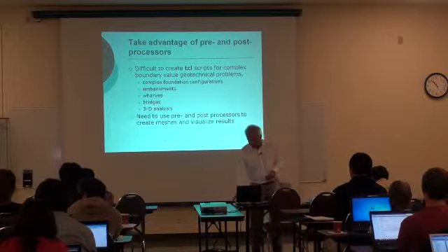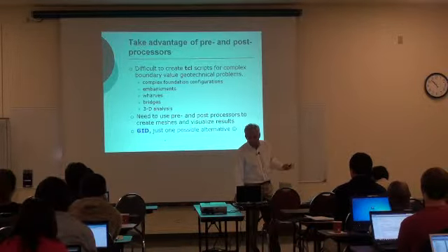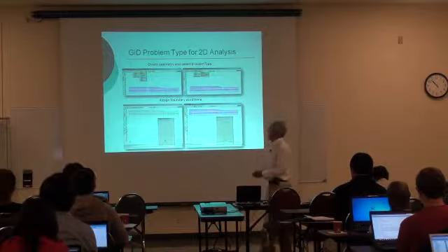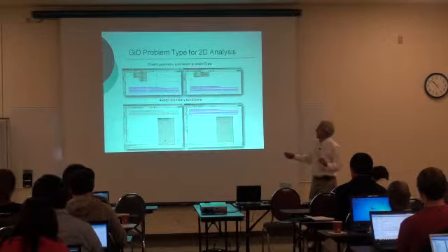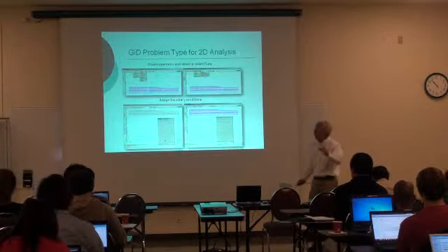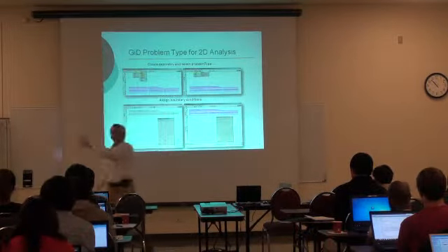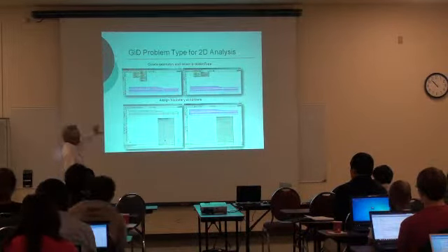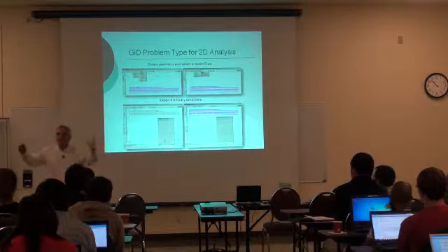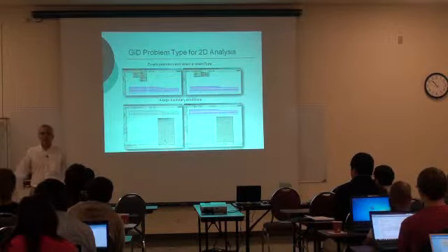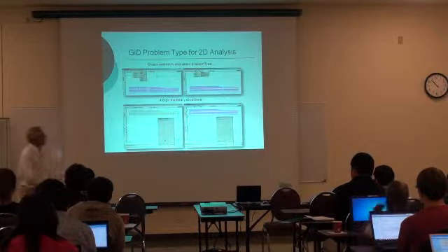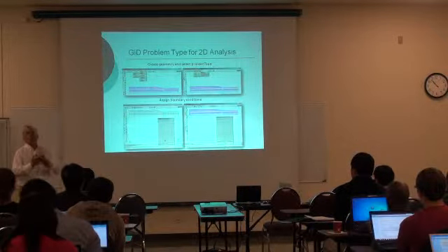So that's why you need to go into the pre and post processors. And GiD, as I said, is one application. And what we did is to use GiD, as I mentioned. Now, if you try to use GiD and you think, oh, I will use GiD and use OpenSees, so I develop my mesh in GiD, now, where is my input for OpenSees? No, you can't. So what we did is to develop what is called a problem type.